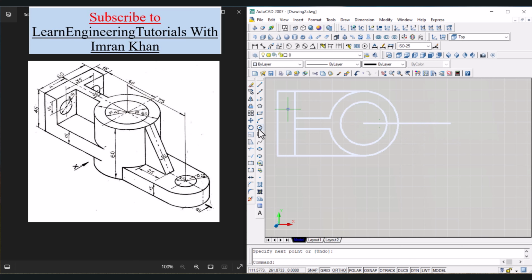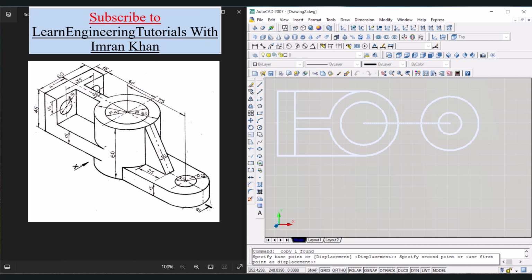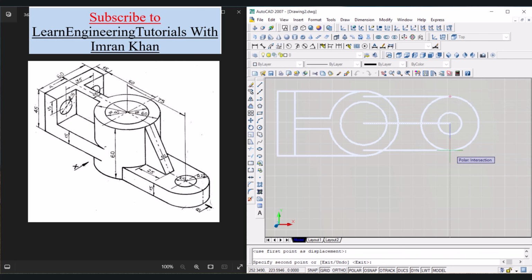Now we have to draw two circles. Click on circle, click on this endpoint and give the radius of 25, enter. Press enter again. Click on this same endpoint and this time give the radius of 10, enter. Click on this line, click on copy, select this point, bring the cursor over to this quadrant, click, and this quadrant as well, click. Press escape.